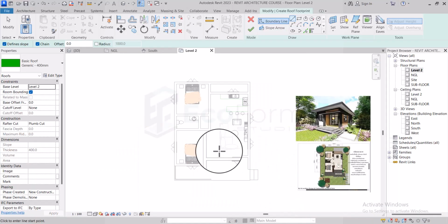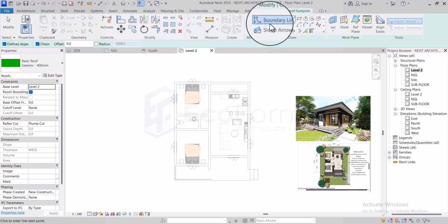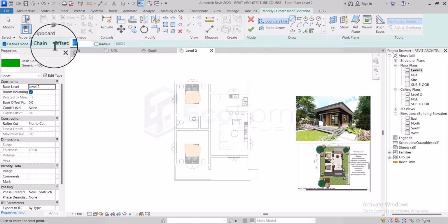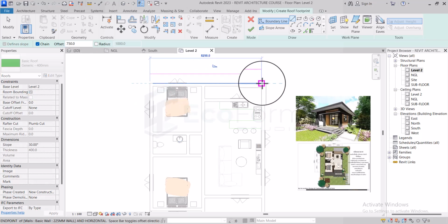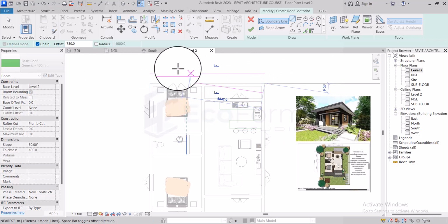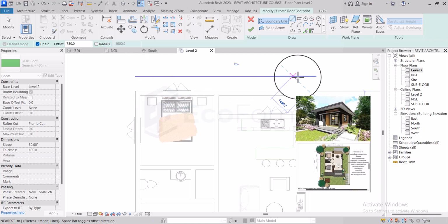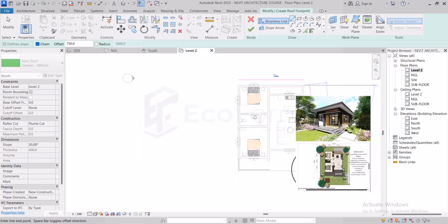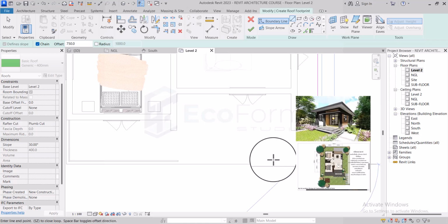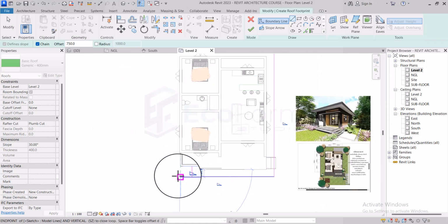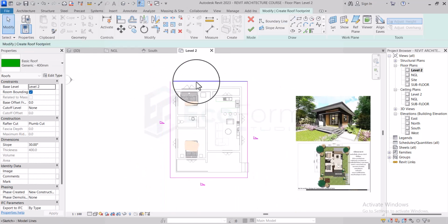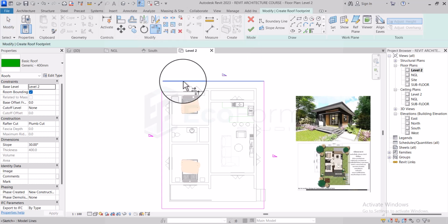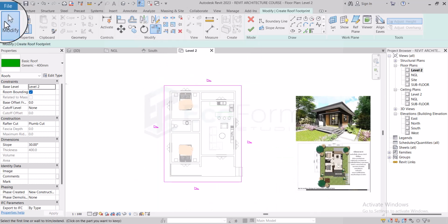Going back to Revit, that means after picking the line, I would select offset and type 750 mm. Then as I draw, you can see I'm drawing on the wall, but it is automatically giving it an offset. So if I draw all around, it's going to offset everything all around. Then I can use Trim/Extend to trim them together.